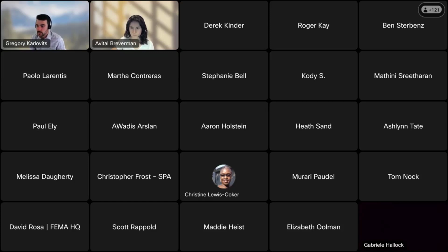Landon is asking a little bit about the sensitivity of the event threshold, the events per year, total events, and number of realizations. So the threshold is going to give you an idea what the smallest storm events are. And if you actually page through them, when you start getting down to a large number of storm events per year, the literature usually suggests 5 to 15 events per year, there actually starts becoming a very small amount of variability in the more routine events. They tend to be much more uniform in time and space, and so you have a hard time telling those storms apart. So that lower bound isn't really a controlling mechanism.